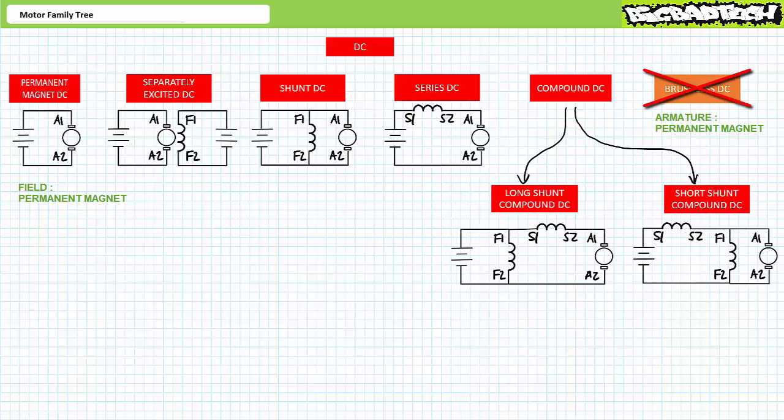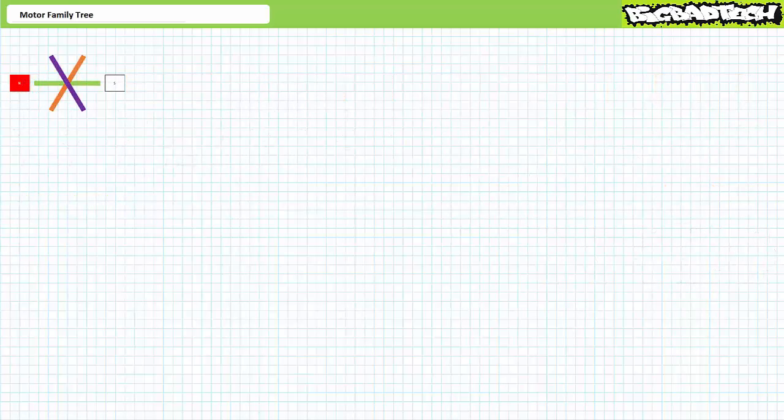All these types of traditional DC motor configurations produce different speed and torque profiles and inherent advantages and disadvantages, which we'll discuss in greater detail in later lectures. Today's discussion is intended to be introductory in nature. Let's briefly discuss the mechanics of traditional DC motor operation. Because DC supply voltage is of fixed polarity and does not cyclically oscillate like an AC source, most DC motors are not powered by a rotating magnetic field in the traditional sense, but rather a continuously misaligned magnetic field moving to seek alignment.